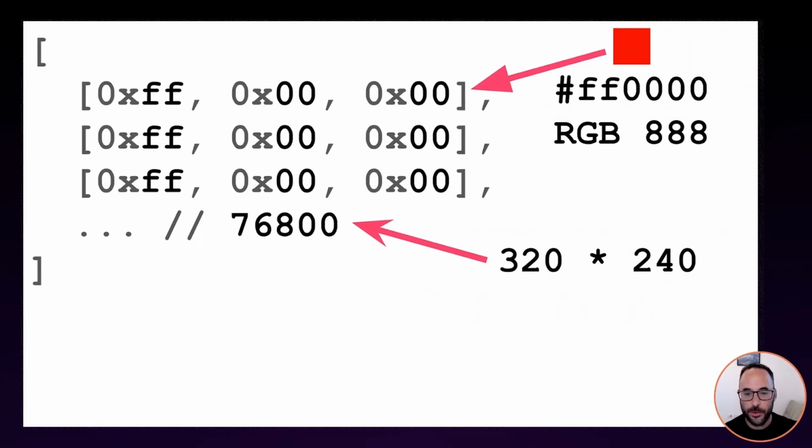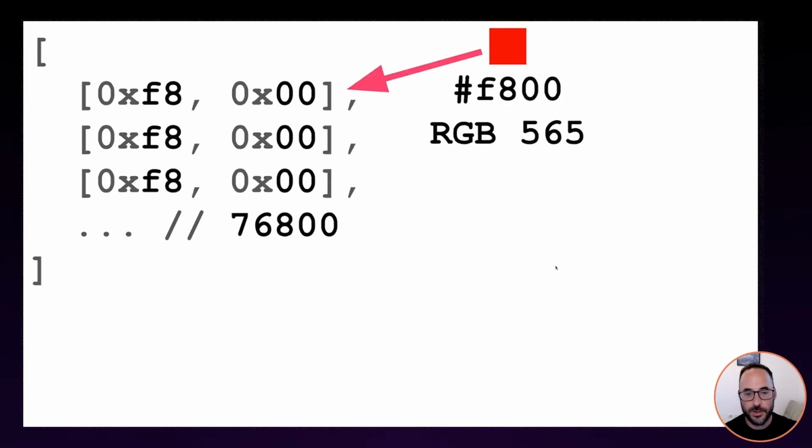Looking at the code of the original display driver in Python that the manufacturer provided, I saw that one of the things it does is it takes this bitmap representation of our image and it converts it to this bitmap representation. And instead of serializing each pixel to 32 bits, it's using only 24 now.